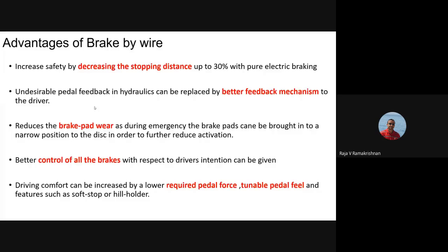It reduces brake pad wear, because since the motor is actually applying the brakes, we can make sure that during an emergency the right amount of brake is applied and brought to the right position, thereby reducing the actuation time so that the wear on the brake pad is less. Better control of all brakes with respect to the driver's intention can be given, because in a mechanical system the driver has to do the work, but here, based on the driver's intention, we can provide a better braking system.